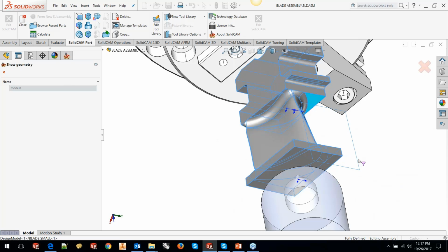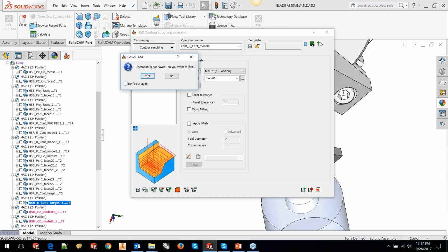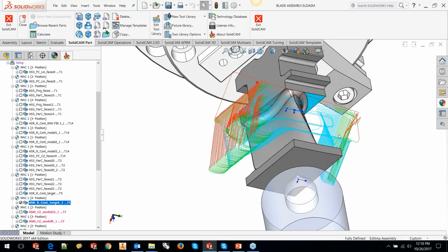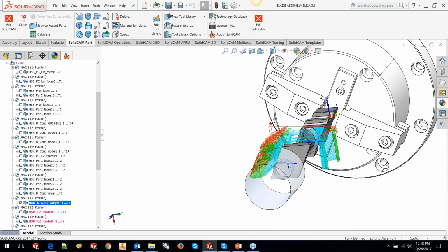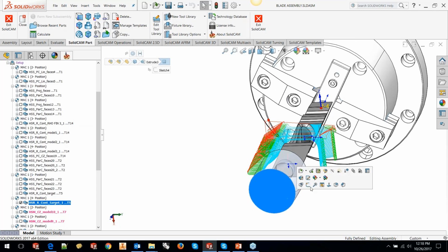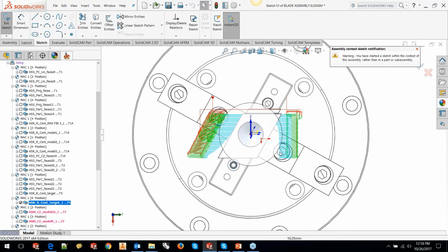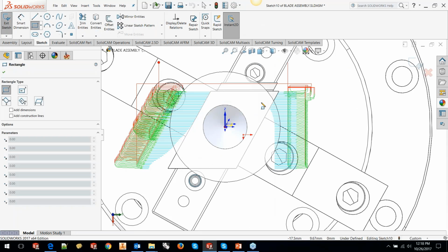But because there's no control on how much the toolpath has to go deep on either side, because once I define my lowest point in Z, it's going to go on either side. So to stop that, we created a surface. Now what I did was to bring back the old toolpath, assuming that there was no surface there. So I have got the surface removed, so the toolpath is now dropping on either side. But I would like to remove some area of this. So create a sketch. And then I'd like to make only up to this point.